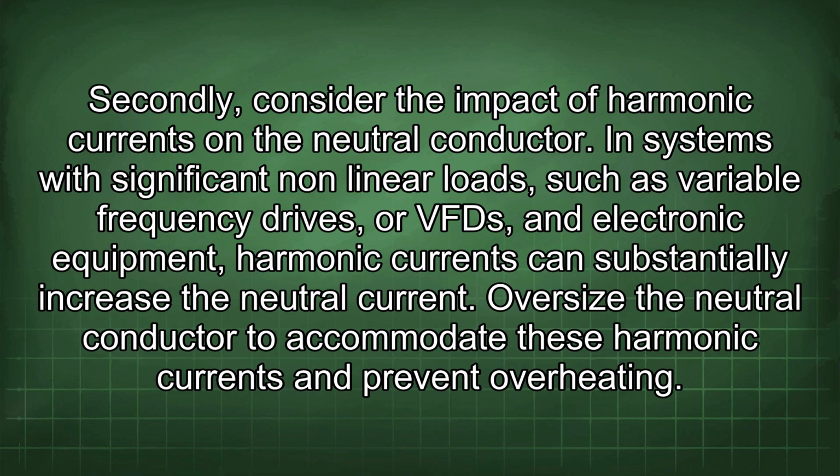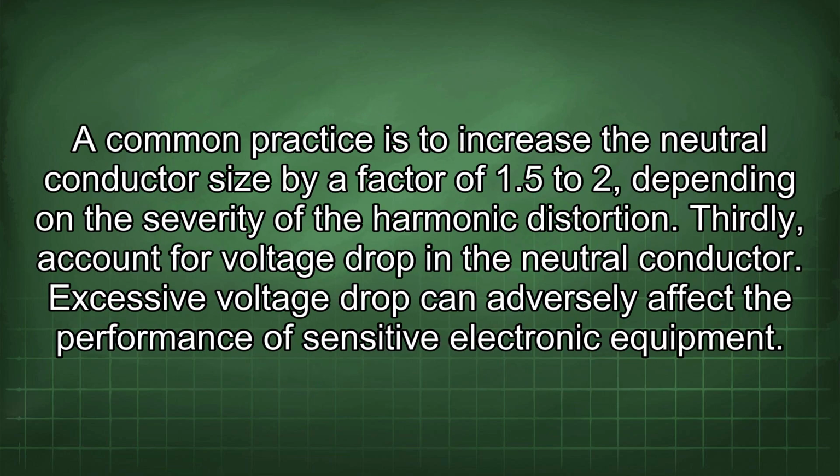Secondly, consider the impact of harmonic currents on the neutral conductor. In systems with significant nonlinear loads, such as variable frequency drives, or VFDs, and electronic equipment, harmonic currents can substantially increase the neutral current. Oversize the neutral conductor to accommodate these harmonic currents and prevent overheating. A common practice is to increase the neutral conductor size by a factor of 1.5 to 2, depending on the severity of the harmonic distortion.